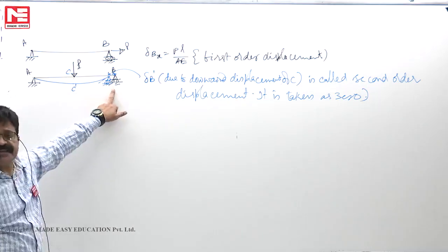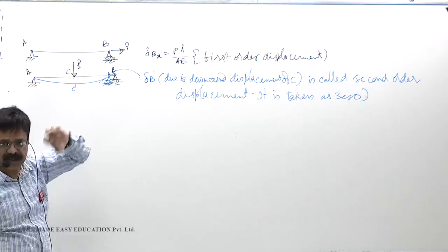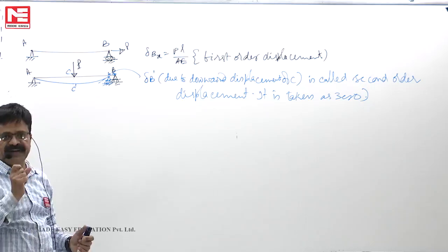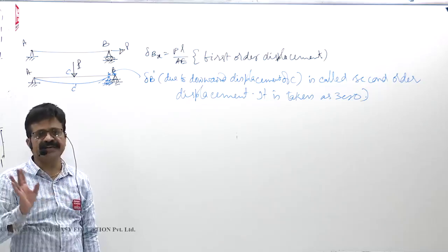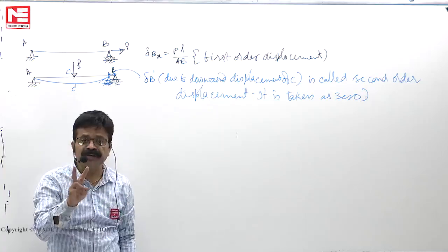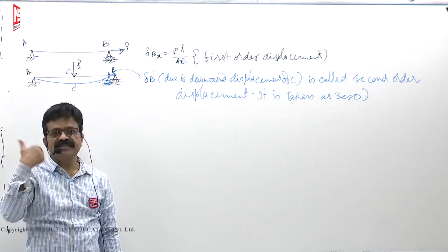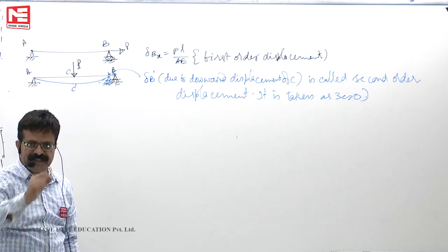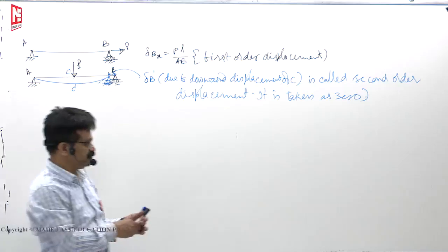So is the case, we take it everywhere, whether you take structural analysis or the plastic analysis, wherever you are getting displacement in terms of theta into some y. Theta is very small, y is also very small, so theta into y means you can neglect. If you have to multiply two displacements, that means displacement square you get, that is called second order displacement. Second order displacement means displacement has power 2. We will neglect because displacement itself is very small.